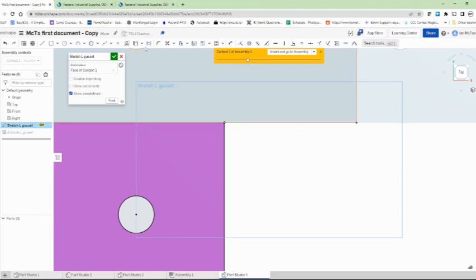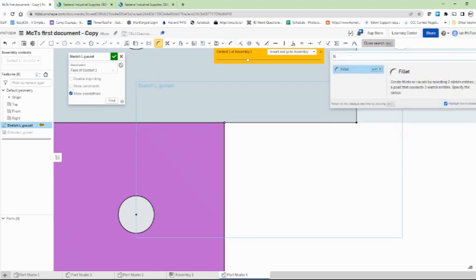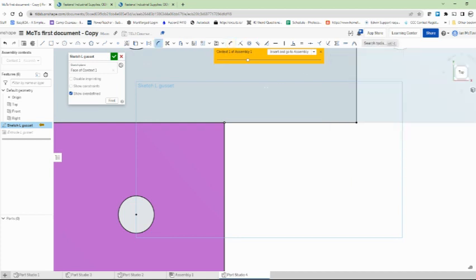So what we do is we design for that. So we're going to use something called the fillet tool. And this is the fillet tool, F-I-L-L-E-T. I often call it the fillet tool. So I'm going to select that tool. And what I'm going to do is click that line, and it's going to ask me for my radius. Well, if I'm dealing with a 1/4 inch bit, that's 1/4 inch in diameter. So that needs to be at least a 1/8 inch radius, 1/8 or 0.125.